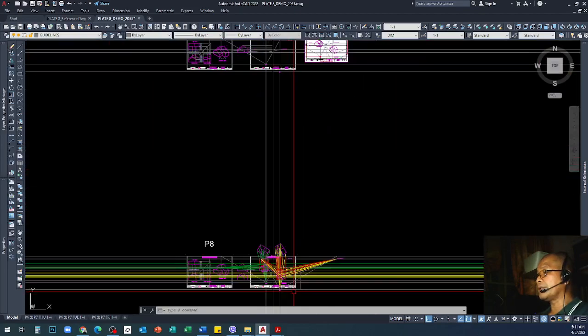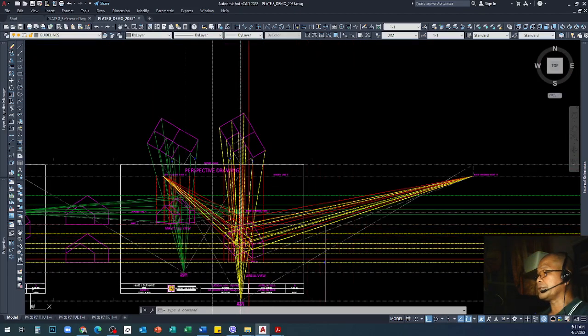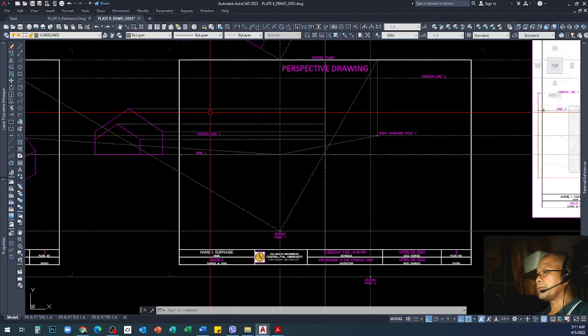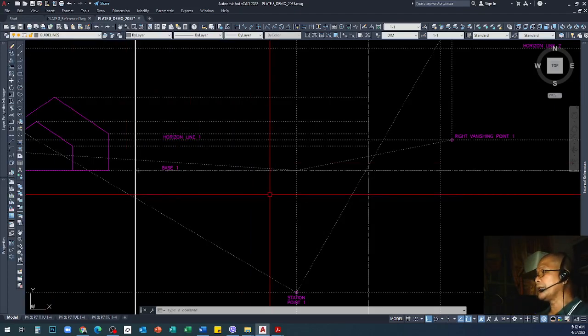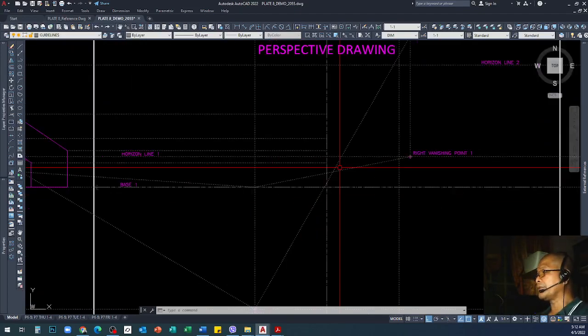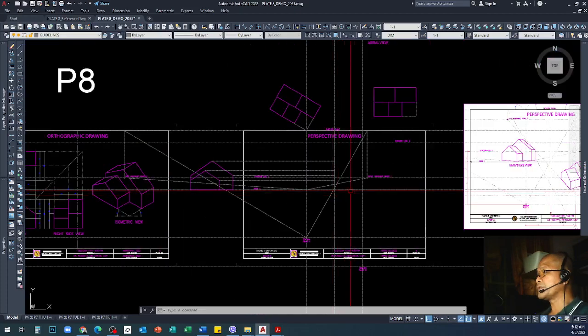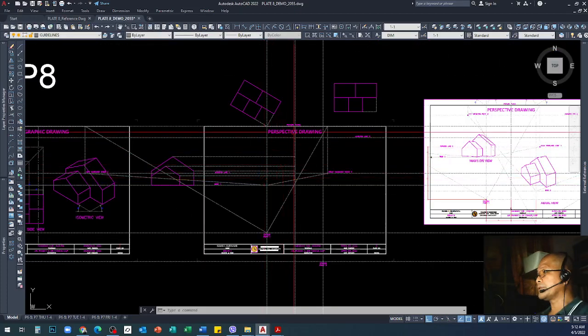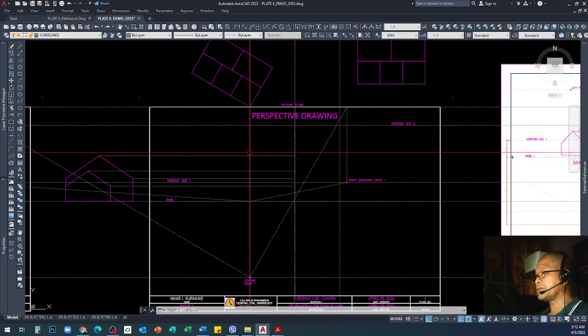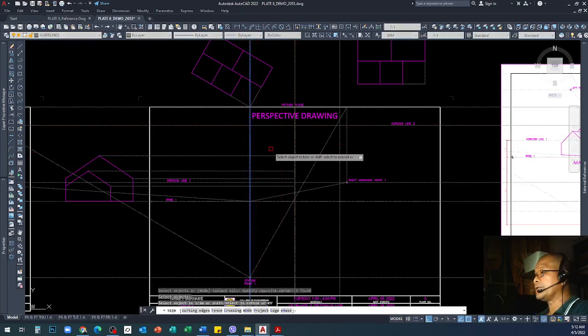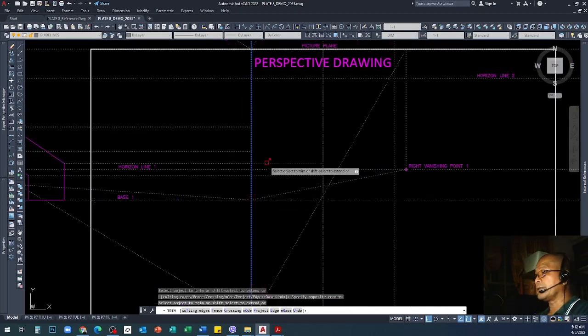That's the part previously that I turned off here. So for mind's eye view I use green 104. You can choose a different color so that you can easily identify which line you need to use. Actually, sorry, I make the lines up to the center line, so you only need those lines here, the projection of your height, like that.